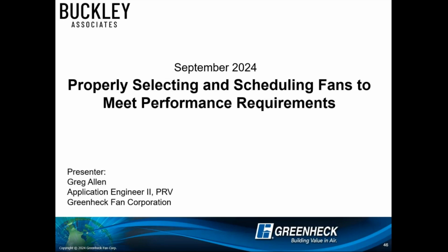So it all depends on the fan, right? Not just the manufacturer of the fan, but the designs of the fan. Some fans, their static efficiency is a little higher. An inline fan will typically have a little higher static efficiency or total efficiency. I was showing you an upblast, so 60% for that design is good.